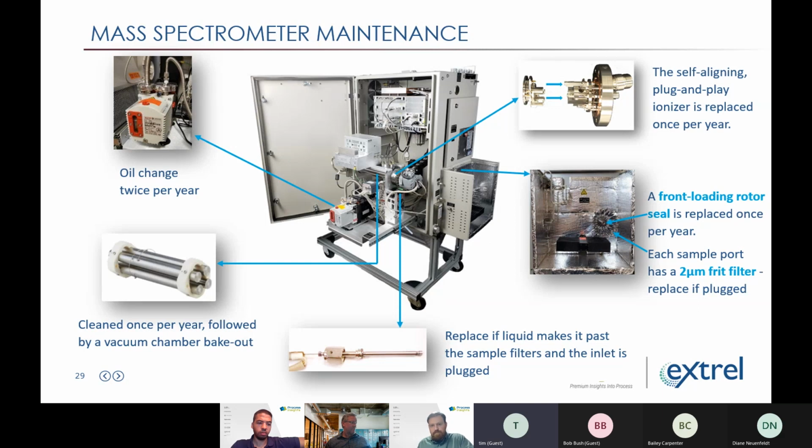We've been in compliance to a high degree in the last 9 months or so. But there was a learning curve, like you were saying, because guys want to throw a bunch of steam at the smoking flare, and you can't do that because it drives your net heating value out of compliance. It's hard to train when you're controlling something that's abnormal. But I think we've got a better handle on it now.